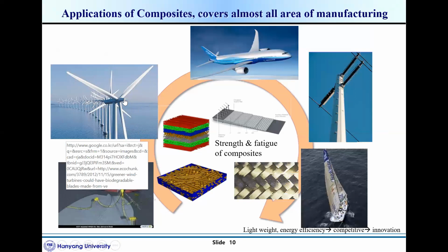The main idea I would like to introduce to the wind industry, in China and Europe, is what I call a synergic skin. On the pressure side and suction side we use a different material. One side carbon, the other side glass, or different angles. A very interesting design, in my opinion. And industry likes that, they would like to try.